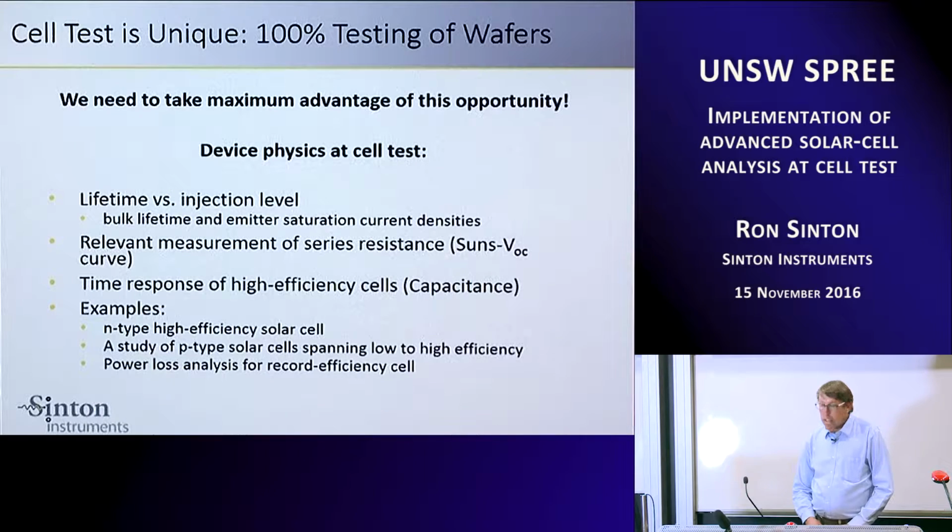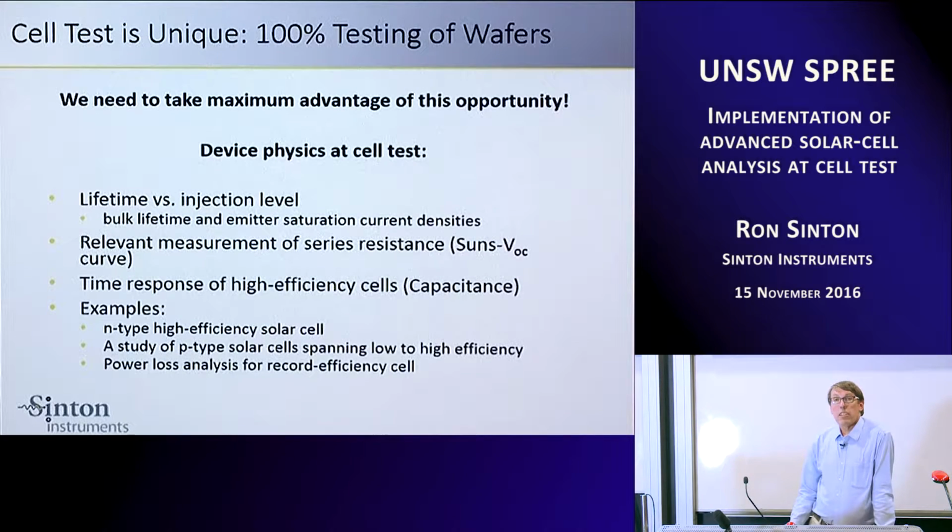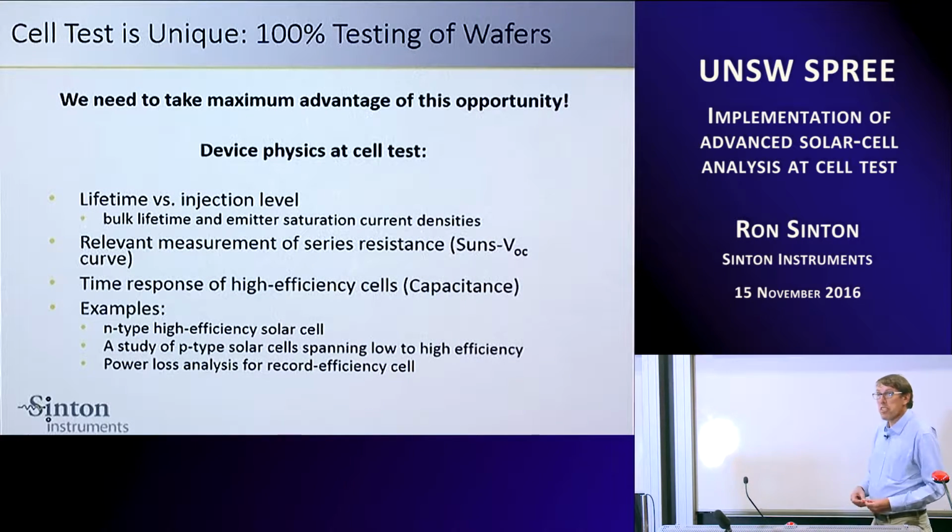And the reason we want to work on the cell test is that cell test is unique in a production line in that it is the only place in the line where 100% of the wafers are measured. It's been difficult putting lifetime testers in the line because it's a little peripheral, but every line has a cell tester that measures every wafer.